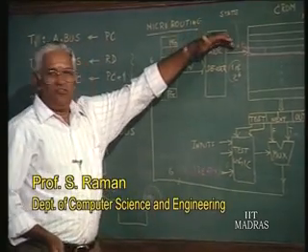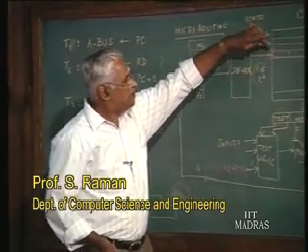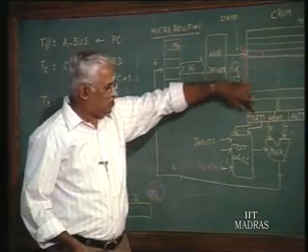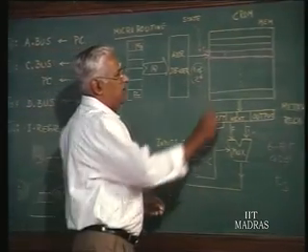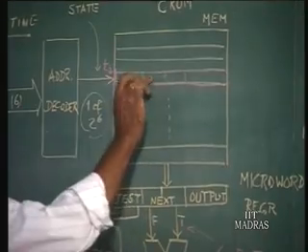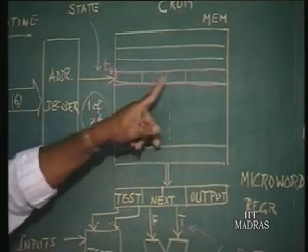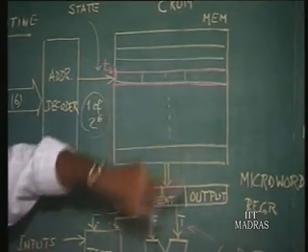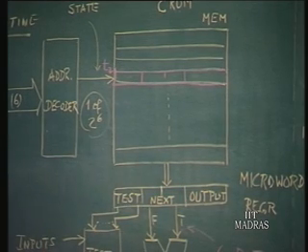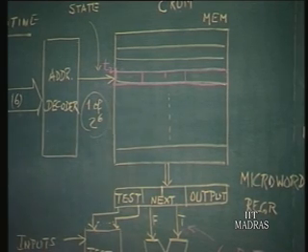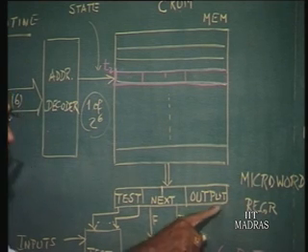So start from any state. In that state, you have information on what the inputs to be tested are, what the possible next states the machine can assume are, and what the set of output signals which must be generated are. In our case, these output signals are all for setting the data path.